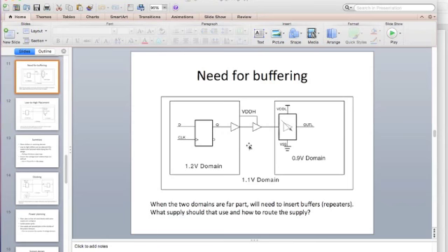You put shielding, you make sure that the high signals which will couple in are not close by and so on. Those are standard practice, and you can do that. So it will just come down to power versus speed, versus whether I need to use a VDDL, whether I need to do some extra work on routing the VDDs or not, and that will decide where I'm going to place the level shifter.